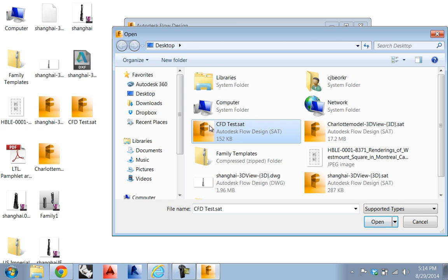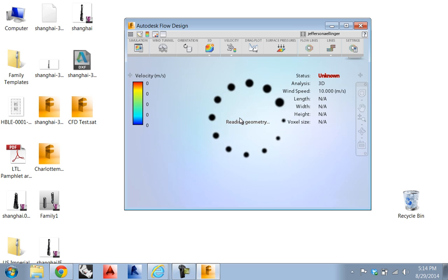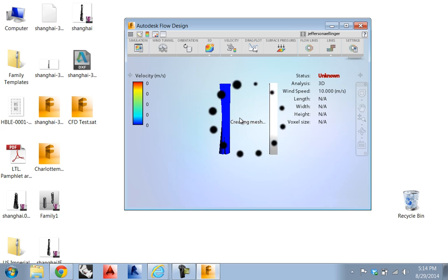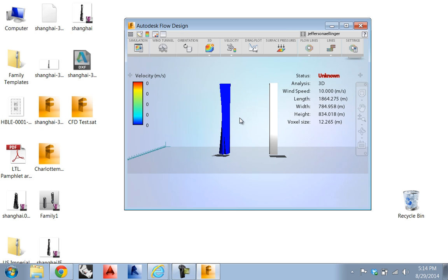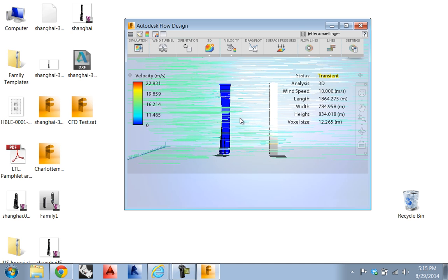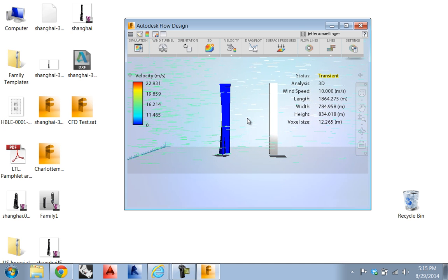But it's pretty good. This will give you a good initial understanding of how the air is circulating, right? But of course, you have to be smart in how you set up your model. You can't enclose the space, and where the intake is and the output needs to be set up so that you build the negative pressures with your solution space appropriately.